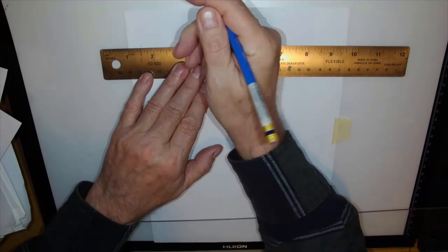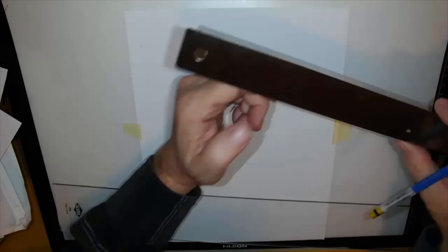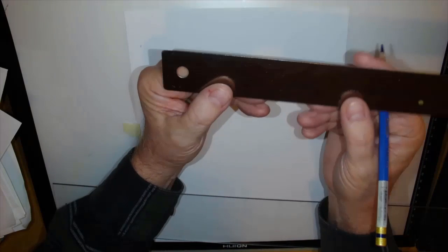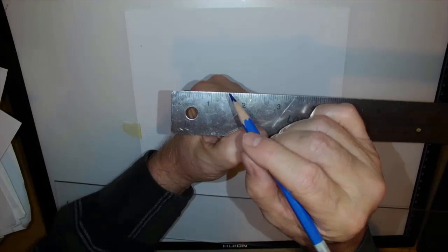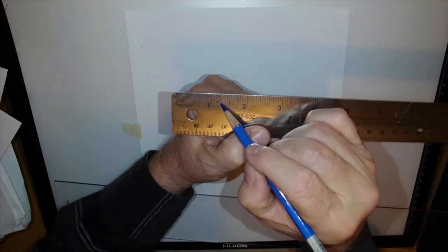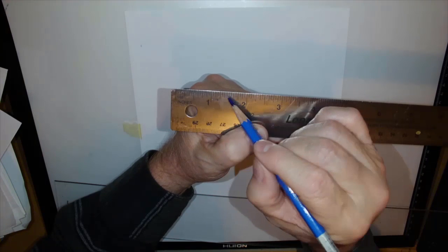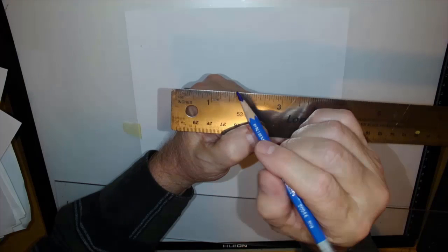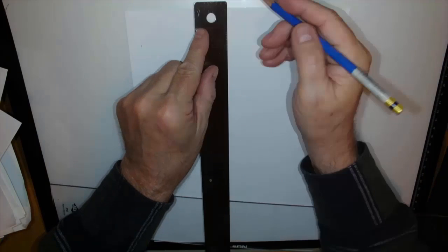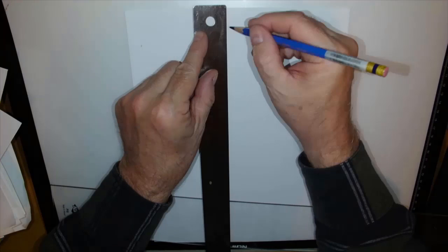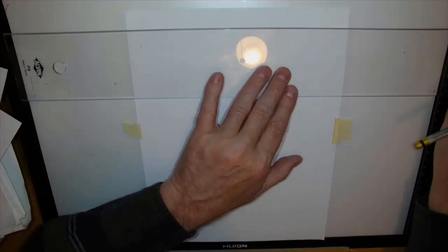I'm going to go a 1/2 inch in. And also, I'm going to be tricky, 3/4 inch from the top. And I'm going to measure that out here, showing from an inch. 3/4 inches is these secondary long lines here. And you'll see there is 3 of them, dividing that up into 4 sections. So 3/4 of an inch is 1, 2, 3, and that's what we're going to measure down from. Okay, so that's so we can box in our views that we're going to be working on. And let me get those drawn across.